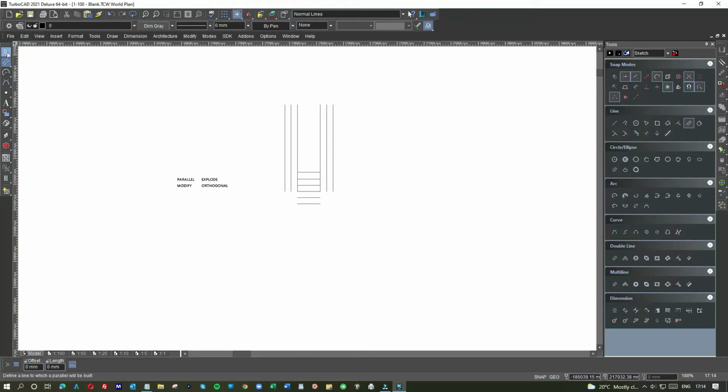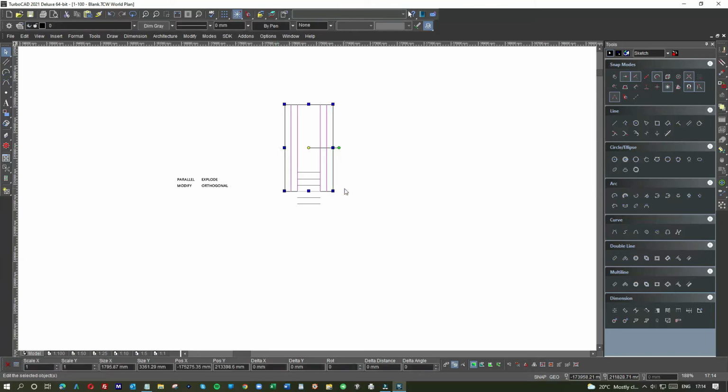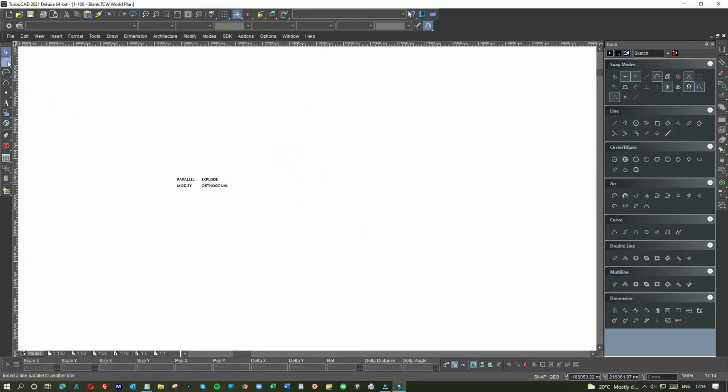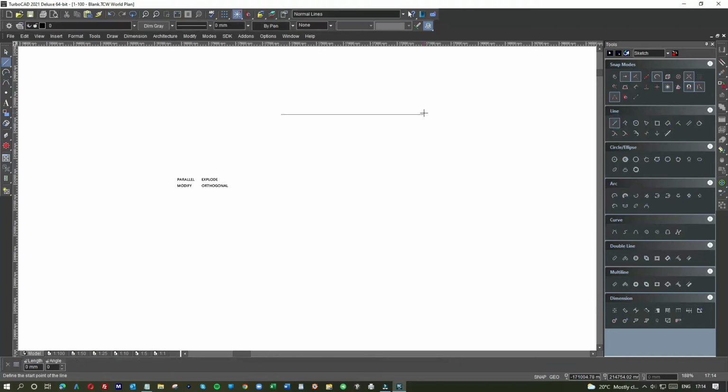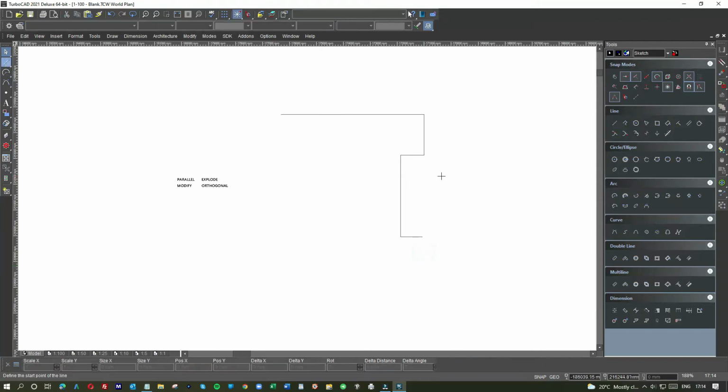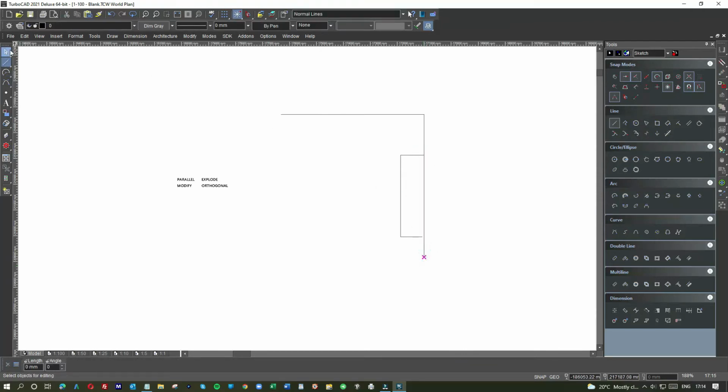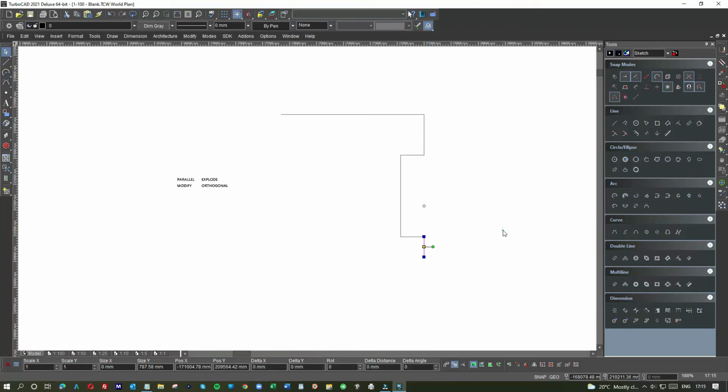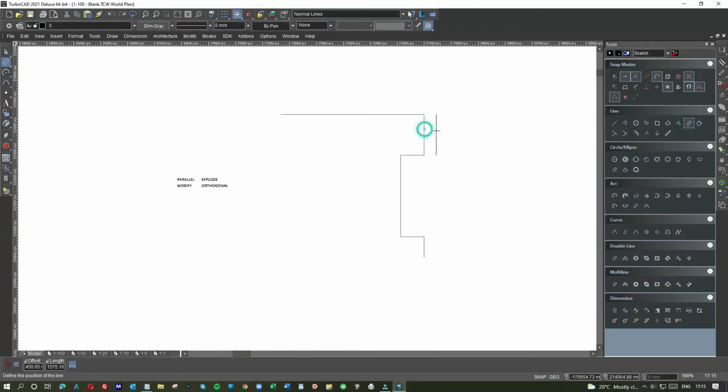Now parallel lines, really useful, loads of bits and pieces, doing walls or anything. So for example, I'm doing a few walls, so let's assume, right, I'm going to build a house, chimney breast. Right, so now, probably wouldn't do it exactly like that. I'd connect over here, make sure it's accurate, connect. So we're going to just show you how useful it is. So now we're going to go parallel. Outside wall for an average house, old house, no insulation in between, 280. So you go tab 280.